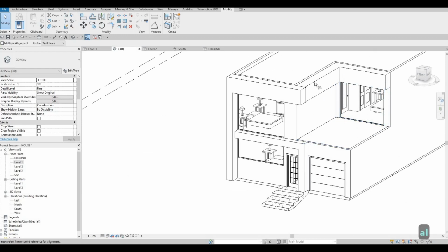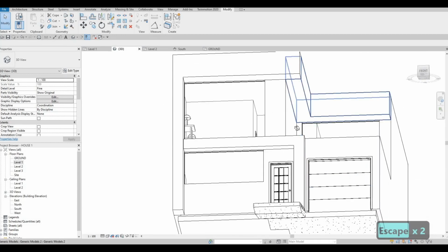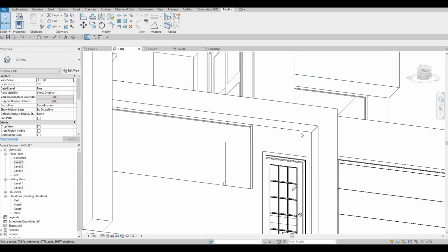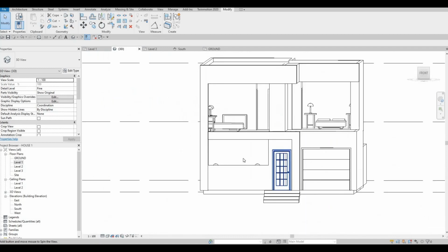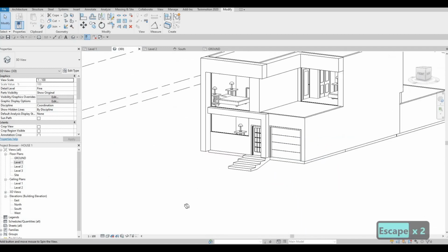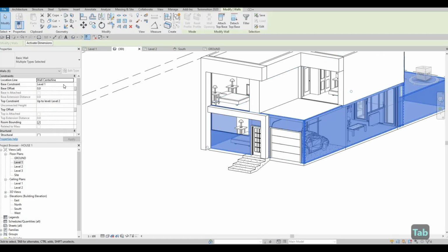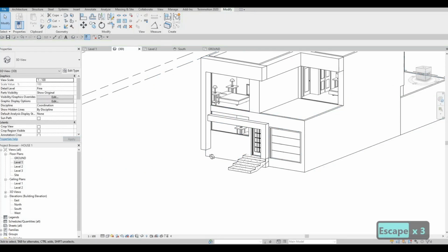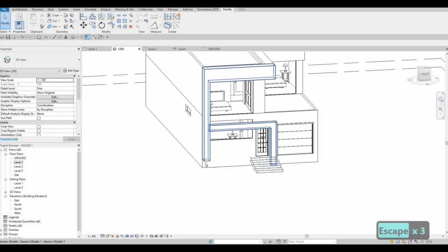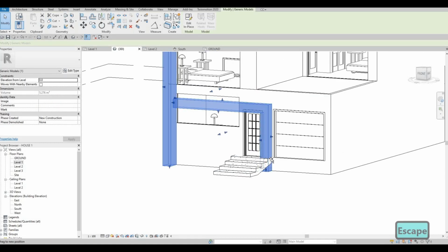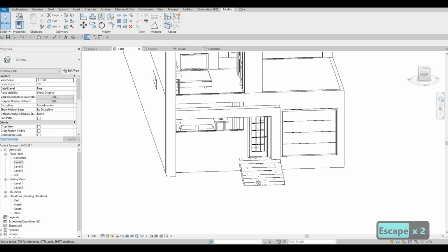But at the same time, we can add in some lights at the top right here. So I'm not concerned of that aspect. So we can actually add it here as well. Next thing is we're gonna select the walls, and then here base constraint to be ground. Now we're extending the wall like that. Here we could just extend it all the way down. For this top, we could just stop from the top right here.